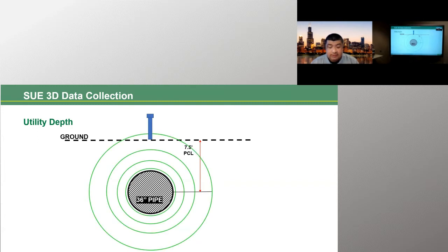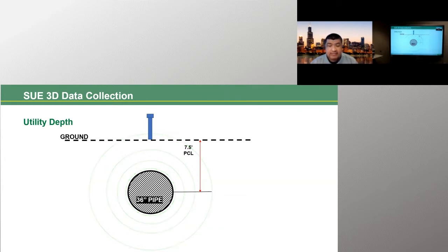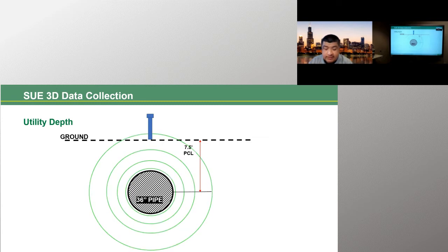With more and more utilities going into the ground, creating congestion, some manufacturers have been adding more enhancements to some of these tools, such as increased power, providing higher quality signal, and enhancements to receiver software to filter out ground noise to provide a more accurate signal and less bleed off. And another cool enhancement is the ability to link the locator receiver with external GPS devices or receivers to enable mapping of the designated utility to GPS coordinates.